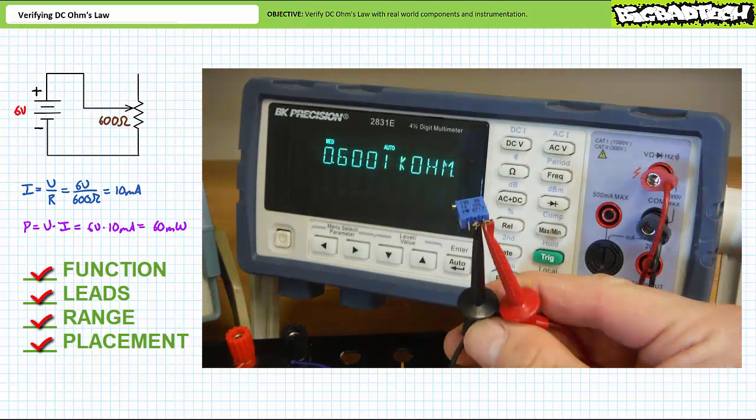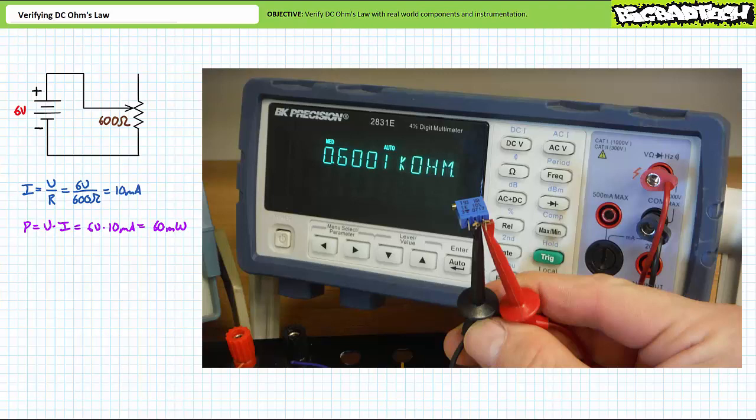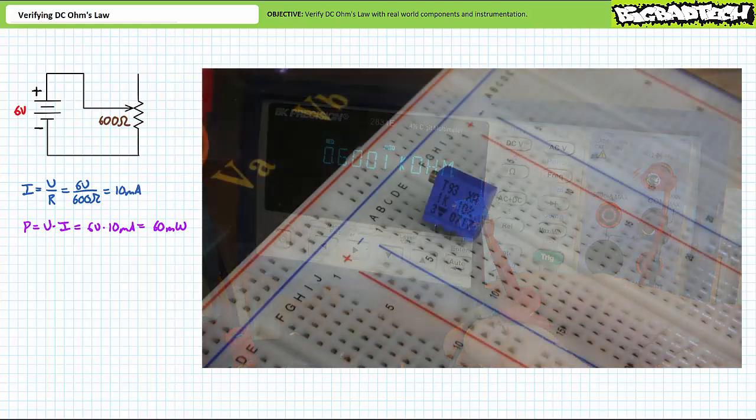Placement. Ohm meters measure the resistance of an element between the two terminals of interest. Our terminals of interest for a 3-terminal potentiometer are one of the outside terminals and the adjustable middle terminal. Additional considerations for ohm meters necessitate that the potentiometer be isolated or removed from a circuit and not powered up. A couple turns in the adjustment screw dials the potentiometer to the desired 600 ohms.